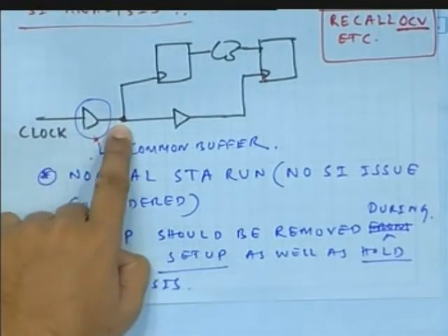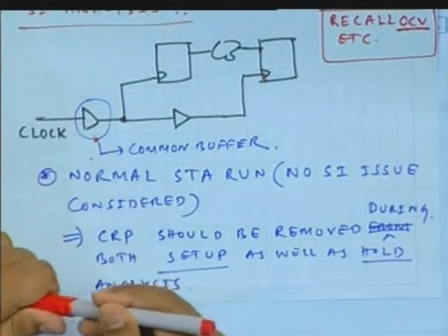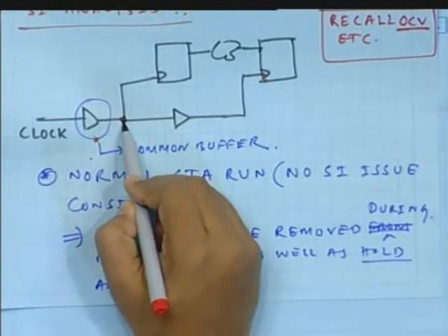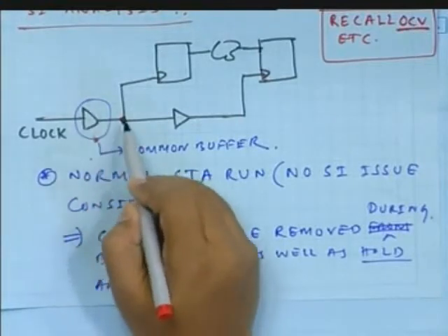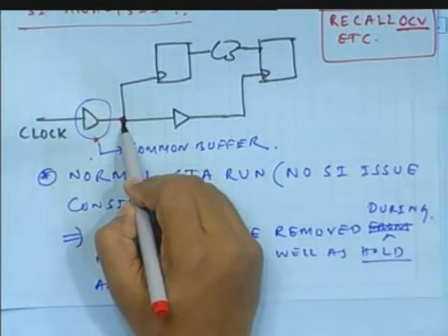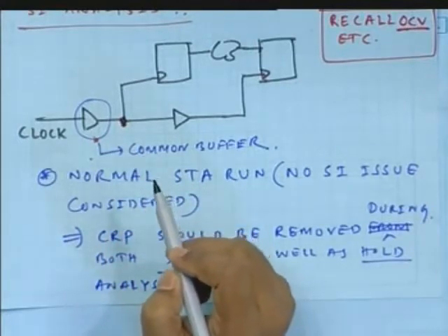And you cannot say that we can take the timing from here for all the signals. If crosstalk affects here before this only, then at this point we are saying we can take from here because crosstalk affects equally for this buffer. Yes, then at this point we can never say that we can leave out this buffer. CRP, yes. You can remove CRP. Any guess for setup analysis?